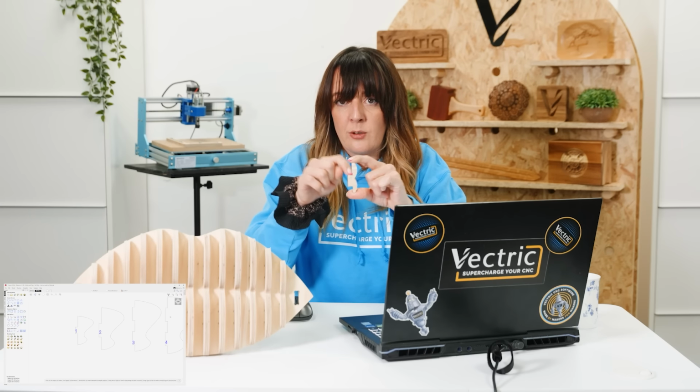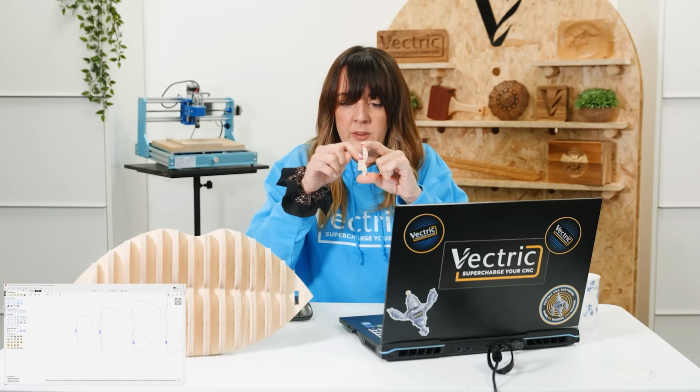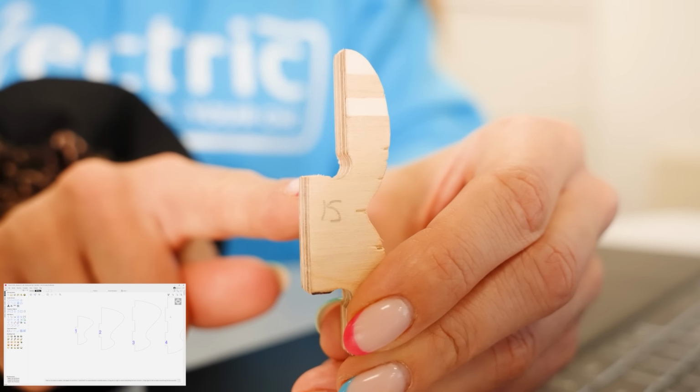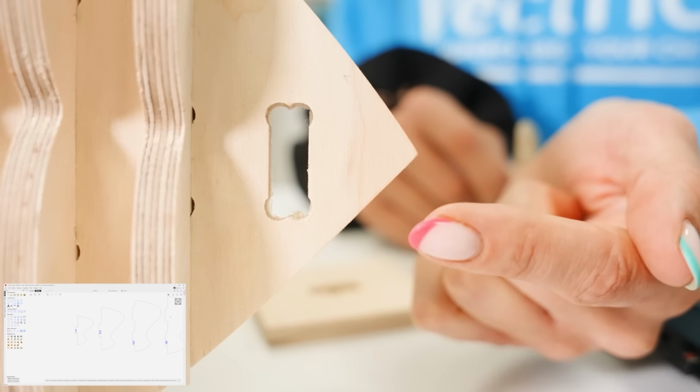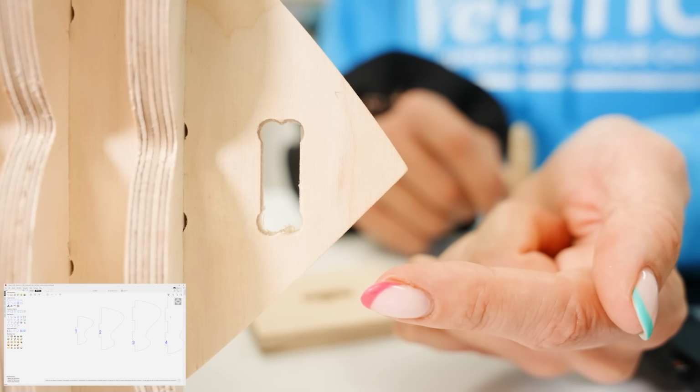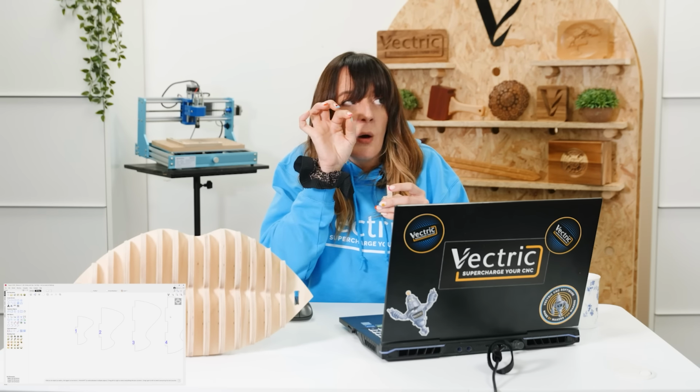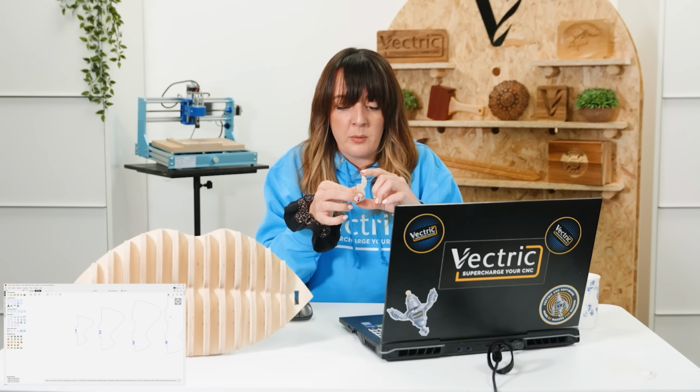So what we need to do is apply dog bone fillets, and what that does is allow us to cut into that corner to ensure that the corner is cut, but you're going to be left with this little dog bone look, which is why it's called a dog bone fillet. And really, at the size that this is, you're not really going to see it, so you'll just see a small little hole in the board, but at the scale that it is, it's not really that visible.